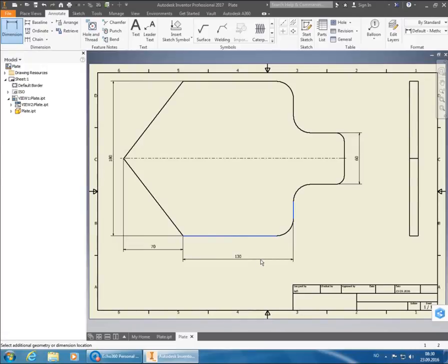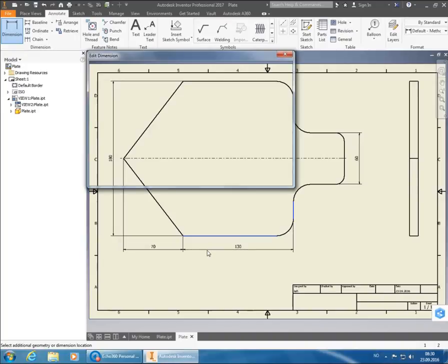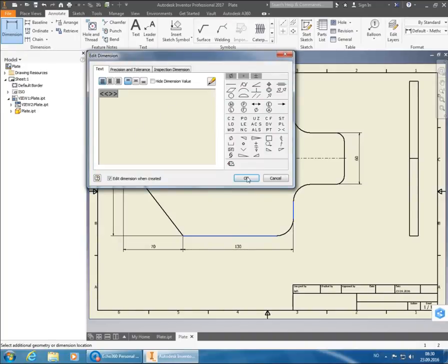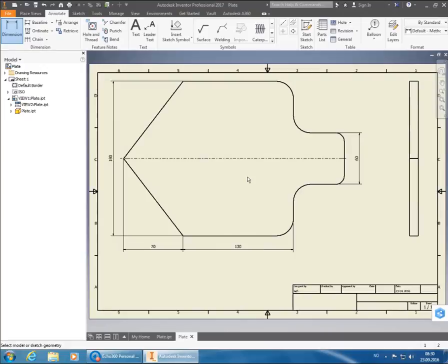And what I want now is to have all of my dimension lines in line. So I want everything showing on one long line here. So what I do is I move my mouse pointer over to the previous dimension. Then you see it turns red, and I get this yellow dot following my mouse pointer around. So if I just pull it back over here, then the new dimension is locked into place right beside the previous one. So click OK. So that looks really nice when you're reading a drawing. It makes it a lot easier to read it.